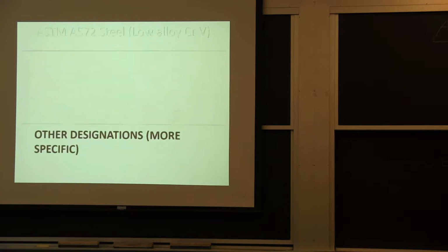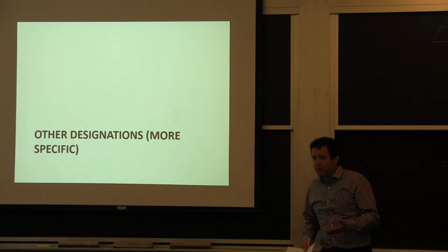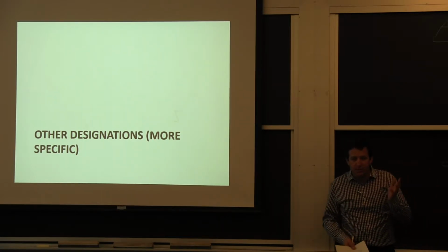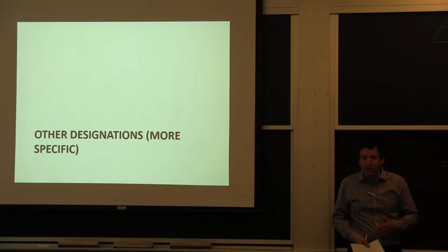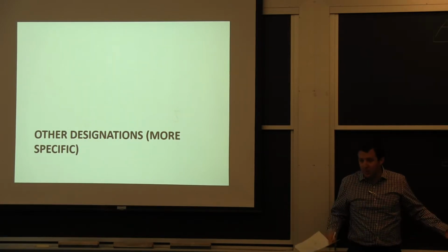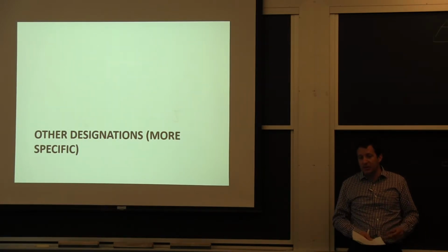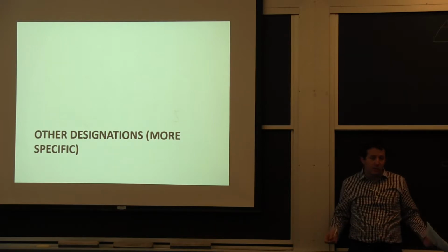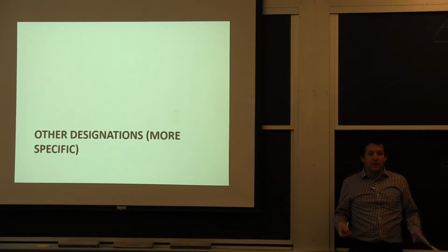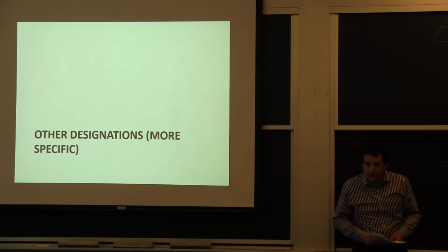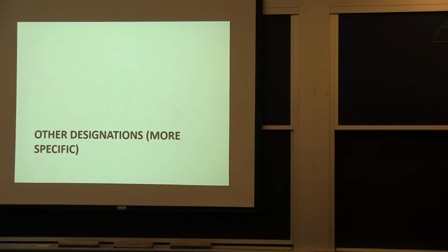Yeah, we covered this. So the basic spec for material, obviously, is chemistry. In steel, you have to worry about impurities. In aluminum alloy, depending what you're looking for, if you're looking for electrical conductivity, you want extra pure. Otherwise, a lot of times you're looking to put alloying elements to increase your properties, because aluminum is so soft.